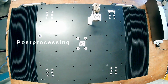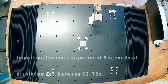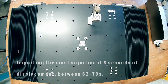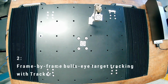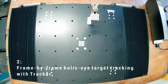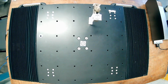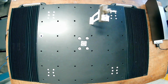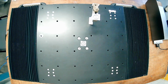mm. Firstly, the most significant 8 seconds of the displacement was extracted from my experiment video. This corresponds to a period between approximately 62 and 70 seconds of the actual Peru earthquake data. After importing this 8-second footage onto Tracker, the motion of the bullseye target attached to the camera-facing side of the mast, which was itself attached to the structure, was tracked frame by frame across the 8-second interval, with the calibrated system calculating the displacement from the start position at that frame.